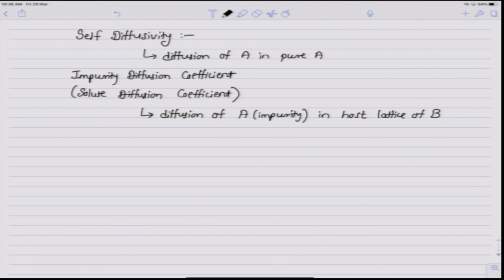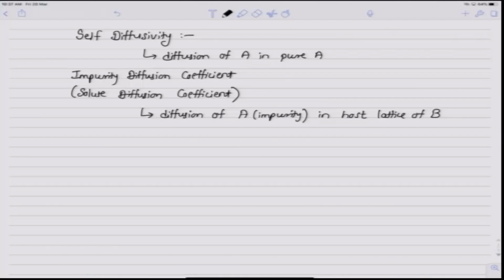Now the self diffusion and impurity diffusion are essentially the diffusion phenomena that occur when there is negligible concentration gradient. That is, these terms characterize the diffusion in a homogeneous alloy. Now when there is concentration gradient present, then we also need to take into account the cross effects of different concentration gradients which we have gone over, and then we have to define different diffusivity terms. So when the concentration gradients are present, we would like to define interdiffusion coefficients.